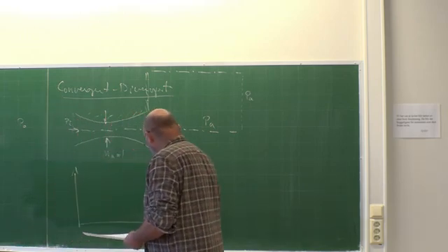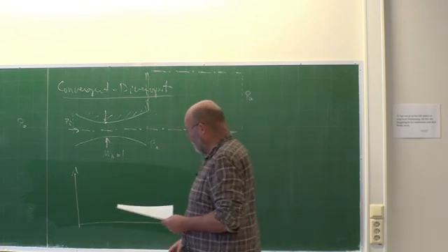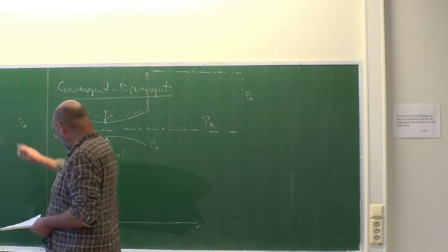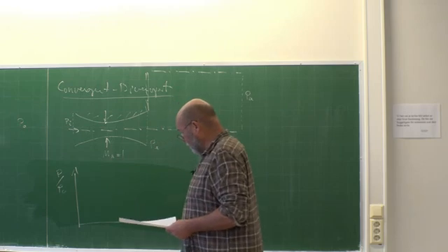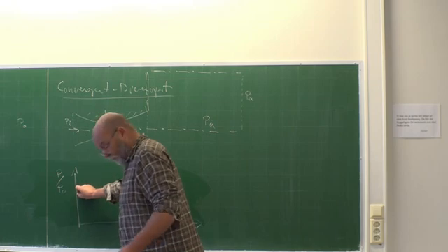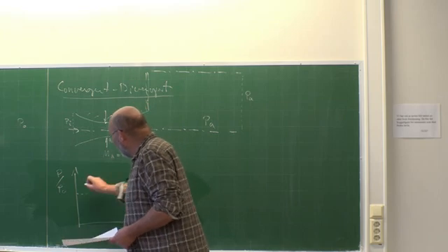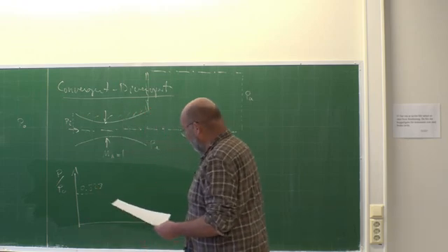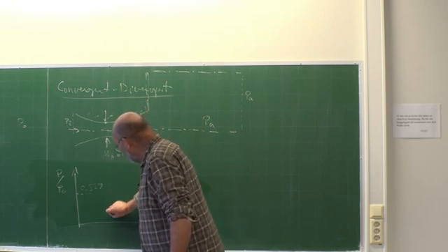So, if we now look at, say, the pressure scaled with this reservoir pressure that we have all the way over here, the critical value from our isentropic relations, that was 0.528 or something like that. Say 0.528 here. And then we have this location here.